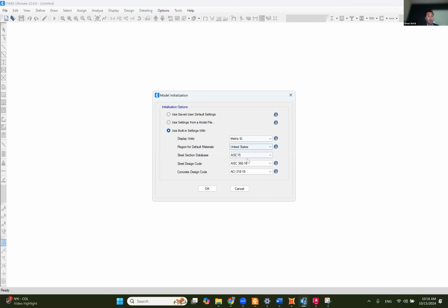And if you are going to do design, and actually most of the firms do design with ETABS, you can choose what standard you are going to use for design. In the US, you use AISC for steel design, and for concrete, you use ACI. All right, so I'm not going to do design, so I don't care about design much. I'm going to keep them, and then I'm going to hit OK.